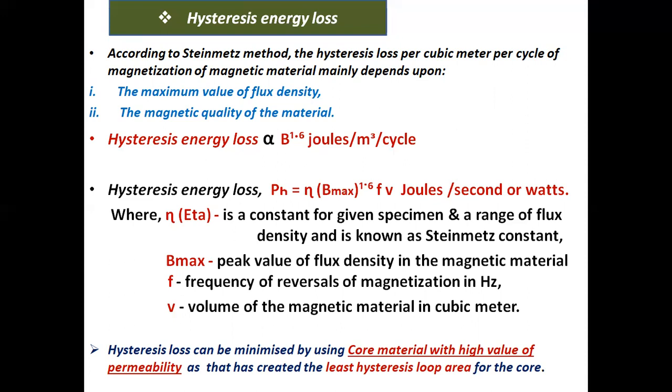Hysteresis loss can be minimized by using core material with a high value of permeability, as that creates the least hysteresis loop area for the core. If I restrict the hysteresis loop area, automatically the hysteresis loss will be minimized.